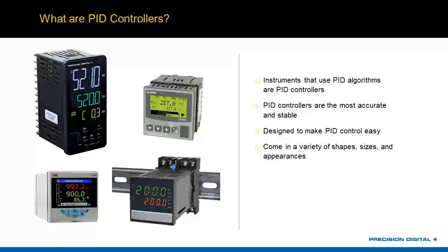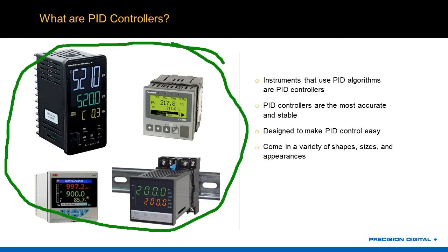A SCADA system, a program running in a control room, could have PID elements in it. You could probably have PID elements in LabVIEW. Anything that implements this PID algorithm to get an output and use that to drive a system is a PID controller, technically. However, generally, people are talking about things that look like this. When someone says, hey, I want a PID controller, they don't mean a PLC. They mean a device that looks like one of these devices.